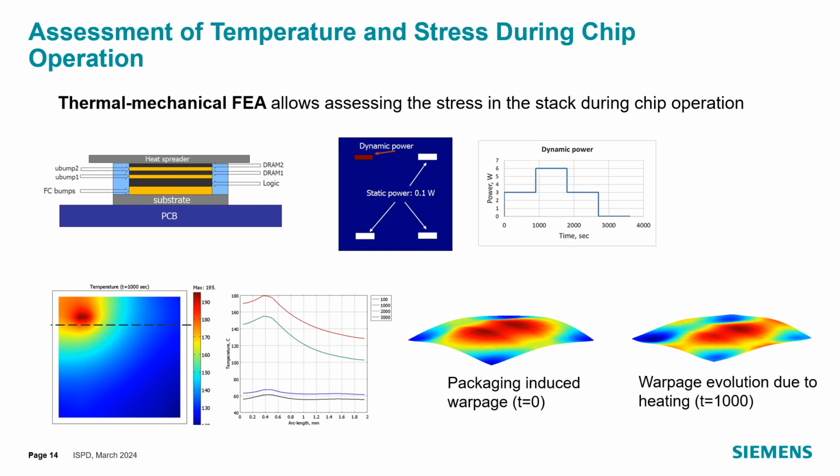The right column maps show the change in die warpage as time increases. The stresses can be damaging, especially in the case of transient temperature, because low frequency oscillations of deformation or stress can cause fatigue of interconnect components.